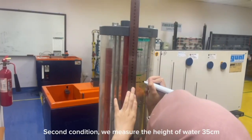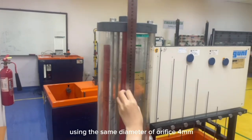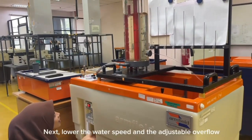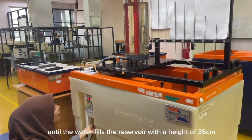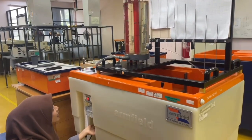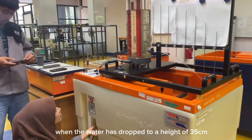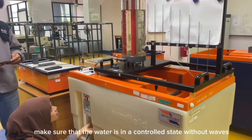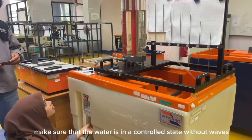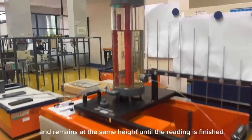Second condition, we measure the height of water, 35 cm. Next, lower the water speed and the adjustable overflow until the water fills the reservoir to a height of 35 cm. When the water has dropped to a height of 35 cm, make sure that the water is in a controlled state without waves and remains at the same height until the reading is finished.